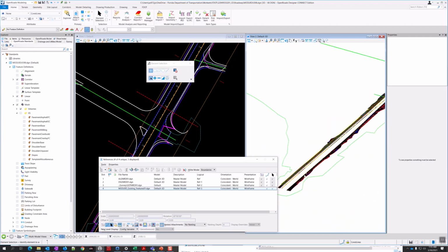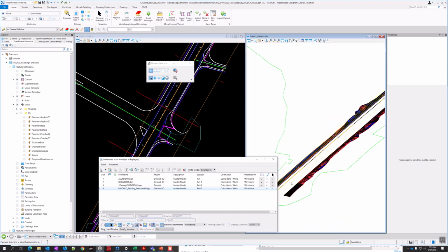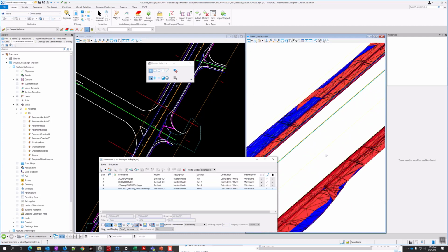So I know it calculated, and of course this is resurfacing, so it shouldn't be calculating anything in the middle there. And if all your definitions are set correctly, you got your overbuild, overlay. See, volume option here is set to none, because this is not counted in earthwork. The base, yeah, that has a volume option. And your pavement asphalt over the widening section.